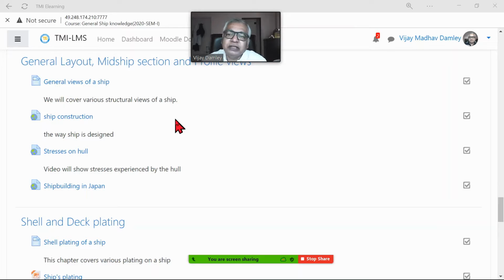Now, how can you achieve something like that if you go one by one with plate welding? You cannot. So it is cut in pieces theoretically. Each team makes its section with perfect measurements. A small minute allowance will be there for metallurgical issues while welding and all, and then they just join them together, one piece, second piece, weld it internally and externally and join the pipelines, etc. So this is how ships are built today.